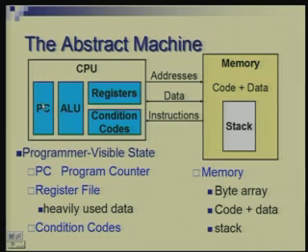So, the way it proceeds is that PC will help in picking up an instruction, ALU will carry out the desired operation, and PC will then point to the next instruction and so on. So, a sequence of instructions will roughly go on in this manner. The instructions will differ from each other in terms of how they are encoded, what operations they invoke, what the ALU is supposed to do. So, there is a controller within the CPU which has not been shown, but that is the one which will guide all these components to do the right thing at the right time.